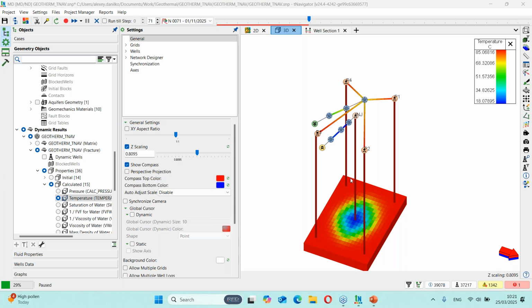Yeah, so the usual practice is to start with the model elements separately. You can start with the subsurface model first, run it, and see how the reservoir performs. Afterwards, you can add the wells and match the well models to real data. We can support this functionality in Well Designer, so you can calculate a temperature profile along the wellbore versus the really measured temperature for producers or injectors. Afterwards, you can move to the coupling.